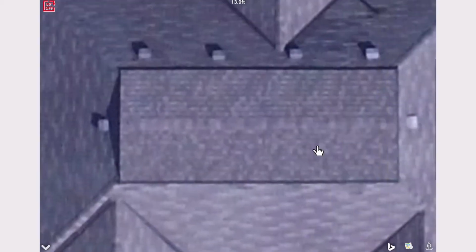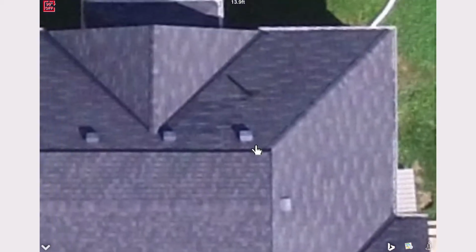The last point I wanted to make here is at 300 feet, you will see that the rakes of this edge are pretty close to straight, but you see how there's a slight tapering there? Maybe on the other side it's a little clearer to see. Oh, this one, it's much clearer to see here. At 400 feet, you all but eliminate this slight tapering that happens with the rake edges and with the hips.